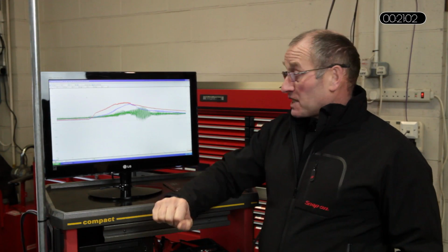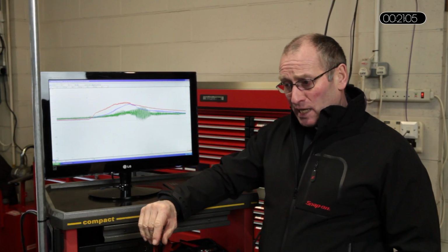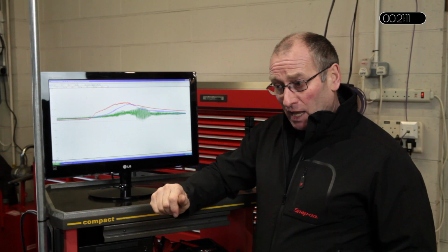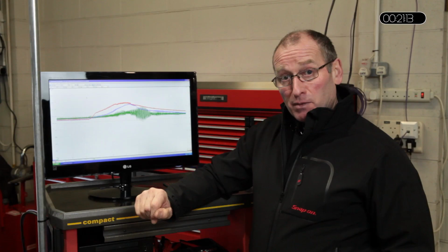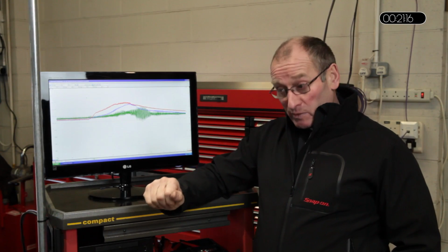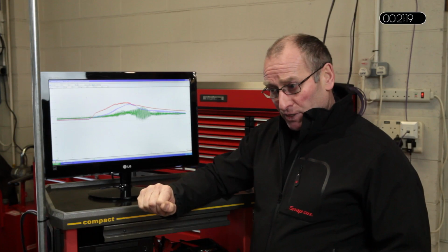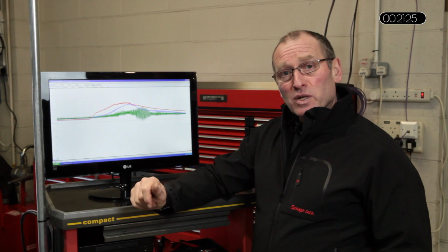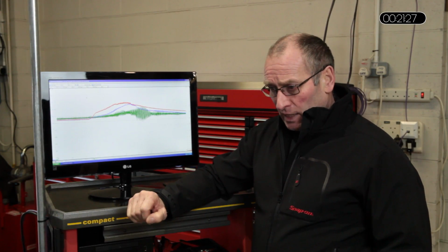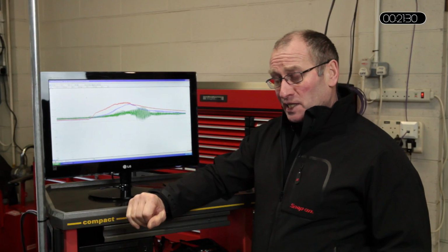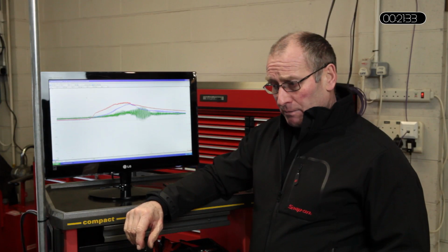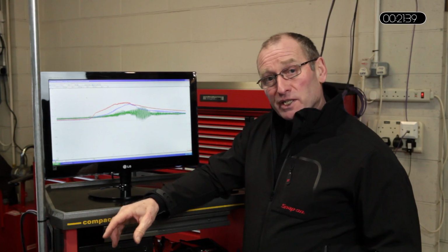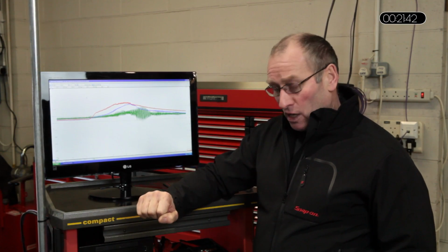Because this is not a new technology, but it's an industry-wide problem that we're all facing, diesels are having, I think it's fair to say, quite severe DPF problems. It will get worse because there are more vehicles now being fitted with DPFs. The drive cycles are not appropriate, a lot of short journeys, slow moving traffic. Sadly, a lot of it is down to the poor quality of oil. We need low ash oil, quality servicing, and perhaps I'm going to suggest servicing at a more regular interval, disregarding manufacturer's intervals because of the environmental issues, not because of the technical issues or specification of the particular oil or vehicle.